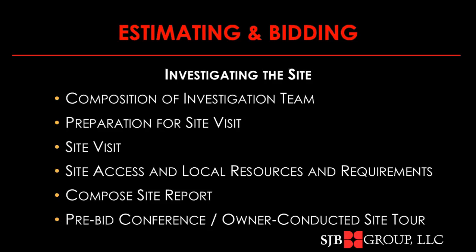As far as site access and local details, how do you get to and from the work site? Is there sufficient labor, or you're going to have to bring labor with you? What's the sources of material? Especially with your large volume of things, where you get aggregate of the various types, where you get your earthwork. Where's the ready mix guy? How close is he to the project?